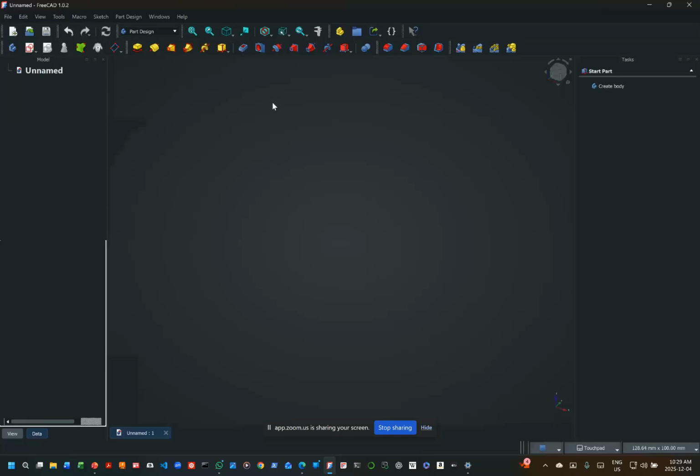Okay, so here now I'm going to do the same drawing all afresh, but at least I'm happy that I've sent you a curated video clip that may be better than what Zoom will show you. But for the purpose of the class, let us go through it step by step. So the first thing is that you open a new document, and then after that, you click the sketcher.